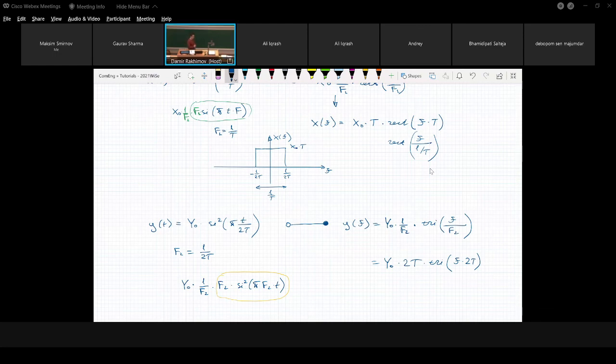Yes, the carrier frequency is fixed and only one, but you select channels based on digital processing. You use digital oscillators, numerical oscillators, numerical control. Anyway, you use simply digital processing to select the channel that you need.